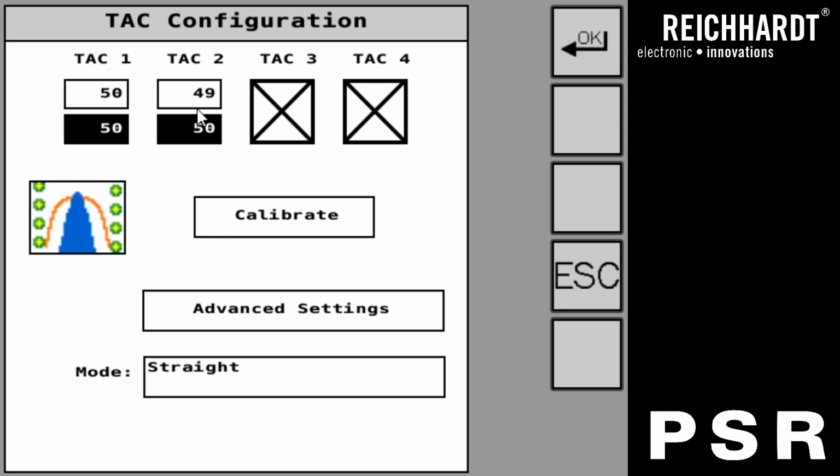And in the case of, for example, 30-inch row spacing, you can have a very limited range in the readings of the TAC sensor. And that's why it's really important. It may not kick out an error code. It's just going to limit the output range of the sensor. It may also eliminate some of the symmetry between the left side and the right side as well, depending on how it's pushed into the sensor. So that's why that alignment's really critical for performance.